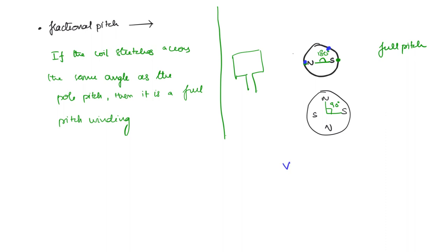Right? For example, if you take the voltage, ideally it should have only Vm sine omega t. If you are taking A phase, it should be Vm sine omega t. But it will also have some additional harmonics. What is meant by harmonics? It is going to have frequency more than the principal frequency. That means if omega is the angular frequency, then you might have Vm sine 3 omega t, that is the third harmonic, and so on. This happens because the machine is not ideal because of a lot of factors, right? Now in order to suppress these harmonics, we make use of the fractional pitch.